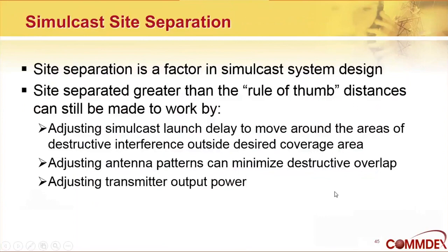So again, this course is not about designing systems, but the people who do design them have to keep all that in mind. Those are rules of thumb. We can adjust the simulcast launch delay, adjust the antenna patterns, and adjust the transmit output power to give us the coverage we want.